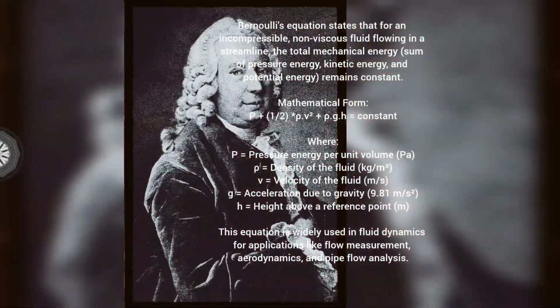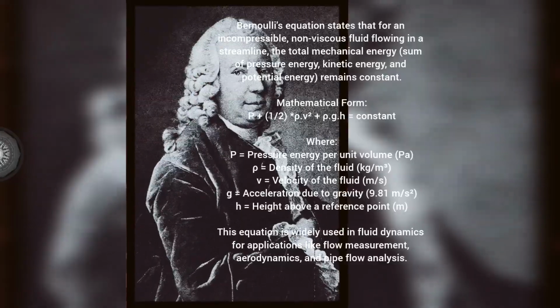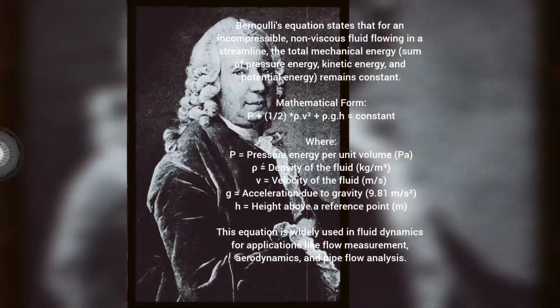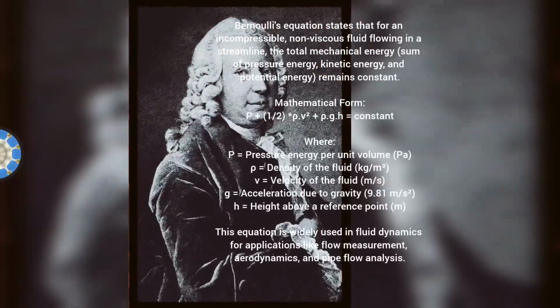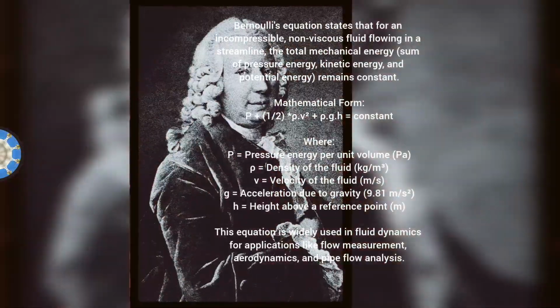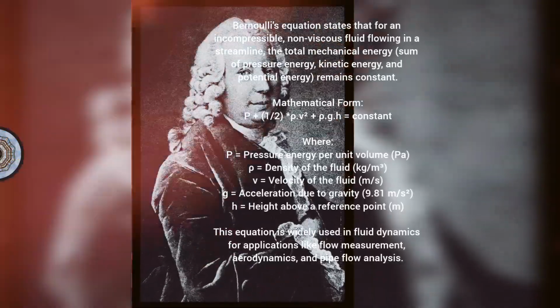That's the cool part. Remember, Bernoulli's equation says faster fluid means lower pressure. So in that narrow throat where it's speeding up, the pressure drops. You got it. Now you've got a pressure difference between the wide part and that narrow throat. Okay, and that difference tells us something. It tells us the flow rate, how much fluid's passing through in a certain amount of time.